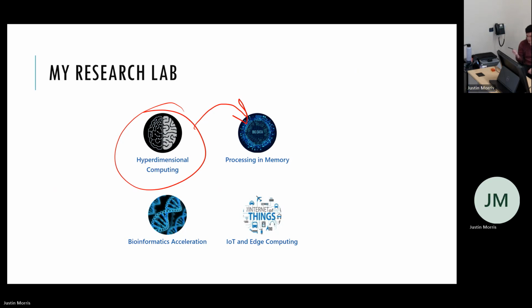If you have a lot of data, then moving the data can be a very large portion of your energy, especially if your compute is very simple. And in hypervector computing, the compute is very simple. All of its operations are bitwise: bitwise AND, bitwise OR, bitwise XOR, things like that.